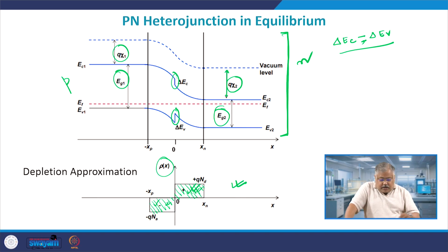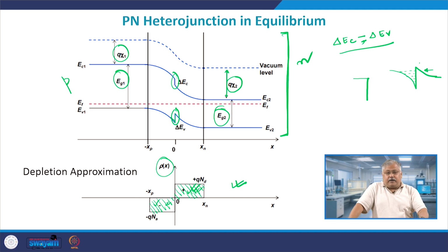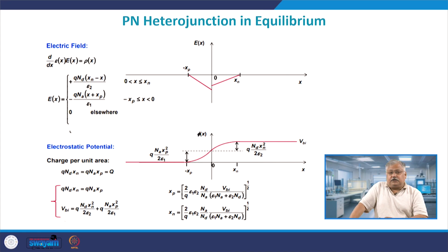Now, if you look very carefully at this particular point, you see you have sort of a triangular shape. So, for an electron this becomes a hill, but you will have these intrinsic energy levels which are basically aligned, and this alignment will be there for all practical purposes. There will be quantum confinement if the dimensions are very small, and therefore electrons and holes will maintain discrete energy levels in case of a p-n heterostructure diode in equilibrium.